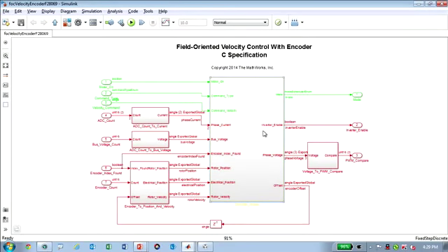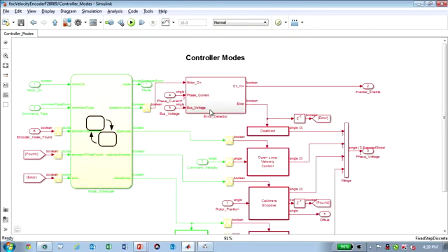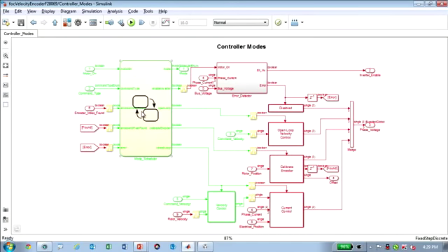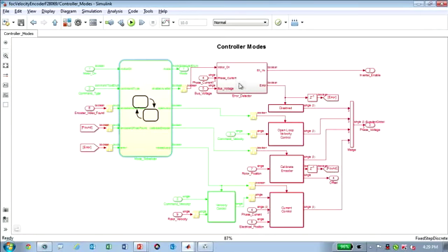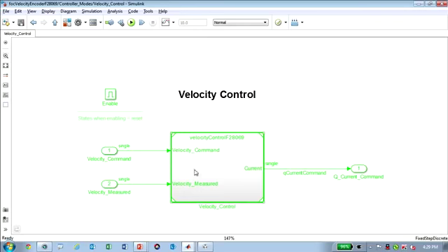Then if I go inside of this thing that's wrapped for the units, what we'll see off to the left is a Stateflow chart. The Stateflow chart's job is to schedule the different components and the tasks. Some of the components are simple enough to be subsystems. For other components, once we schedule them, we'll have a reference model inside of them in order to partition out the design.